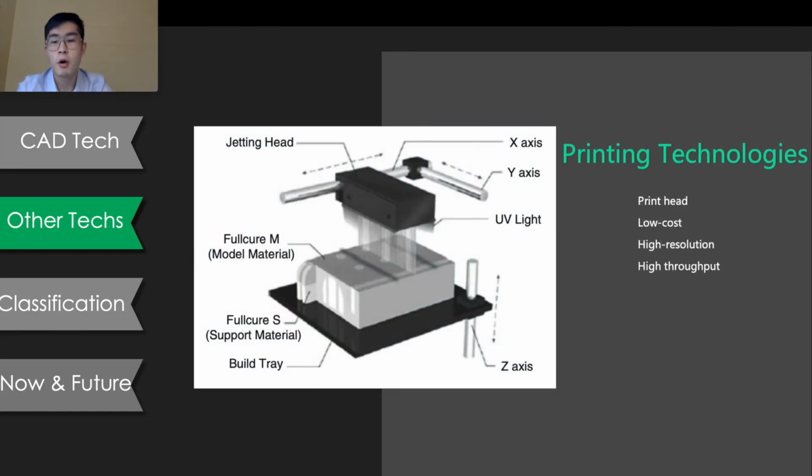Inkjet or droplet printing technology has rapidly developed in recent years. Improvements in resolution and reduction in costs have meant that high-resolution printing, often with multiple colors, is available as part of our everyday lives. Initially, colored inks were low in viscosity and fed into the print heads at ambient temperature. Now, it is possible to generate much higher pressures within the droplet formation chamber so that material with much higher viscosity, or even melting materials, can be printed.